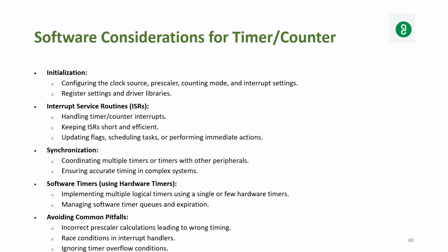Software considerations for timer counters. Initialization: you have to initialize the clock source, prescaler, counting mode, and interrupt settings. All these registers have to be initialized. Register settings and driver libraries.